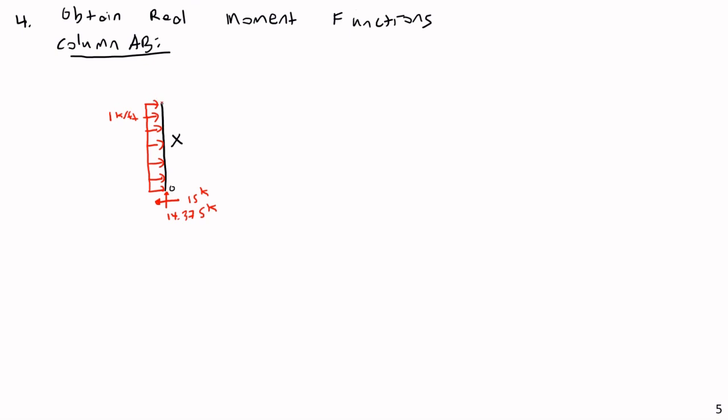Then I'm going to show the shear and moment, assuming them positive according to our initial directions. And for completion, I should show the vertical reaction coming down on this, 14.375. Now, that is an internal force that is revealed by the cut. However, because there are no vertical loads on the column or axial loads besides the joint force and the support, I know that no matter where I cut, the vertical force is still going to be 14.375 kips.